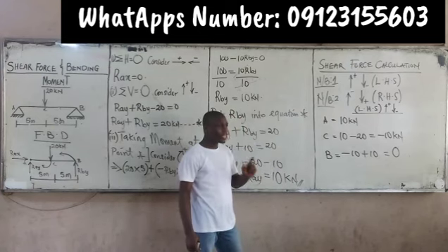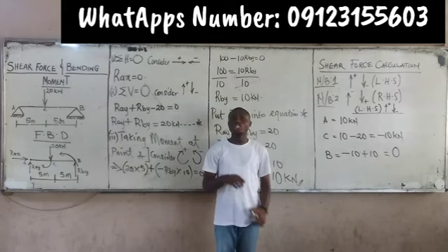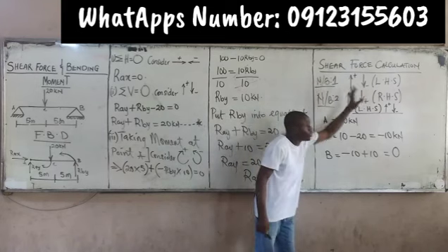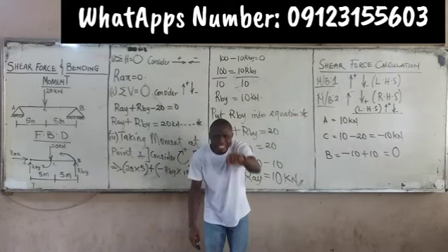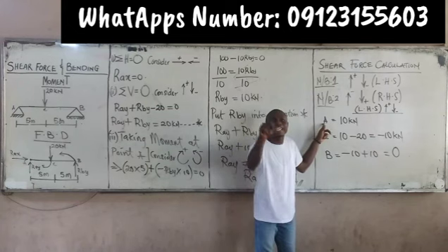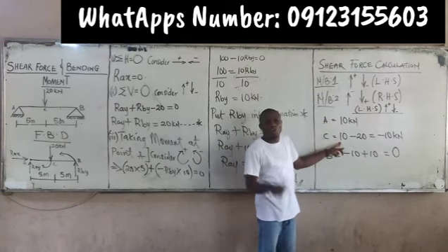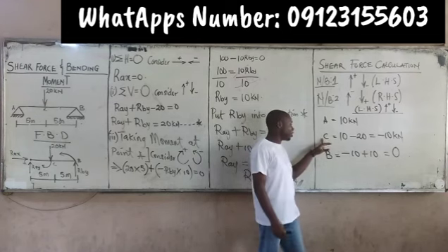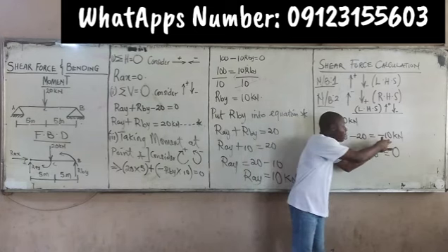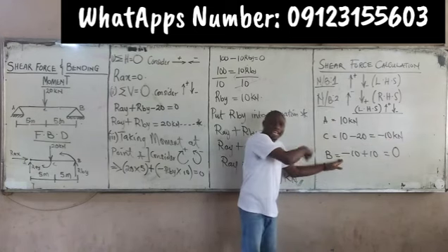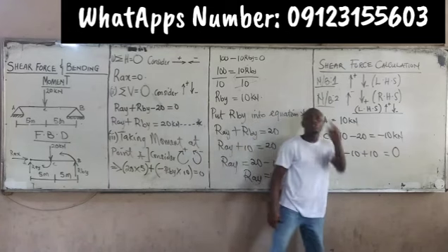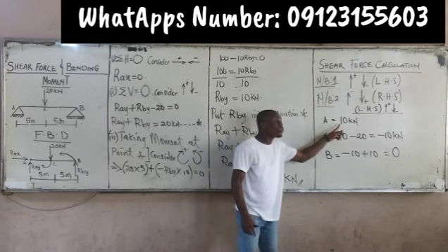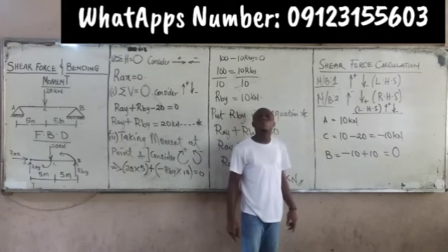Now listen. For shear force, note two things. Number one, note what we just discussed. Number two is that any answer you have from your first calculation, put it down first before you consider the next section. After considering that next section, drop the answer down here before considering the following one. Note also that for shear force, you might not start with 0, but shear force always ends with 0.